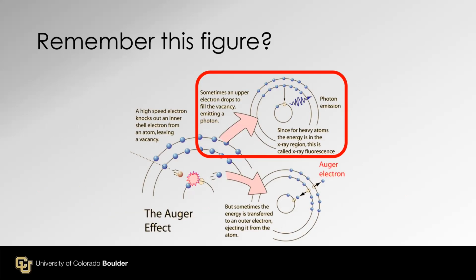To be continued, but remember this figure: in EDS, we are measuring this X-ray. Of course, during the XPS measurement, X-rays are emitted from the surface. Characteristic X-rays should be emitted as well, but the electron energy analyzer cannot see photon emission. There's no way to analyze photon energy. Therefore, it's completely ignored in the XPS spectrum.